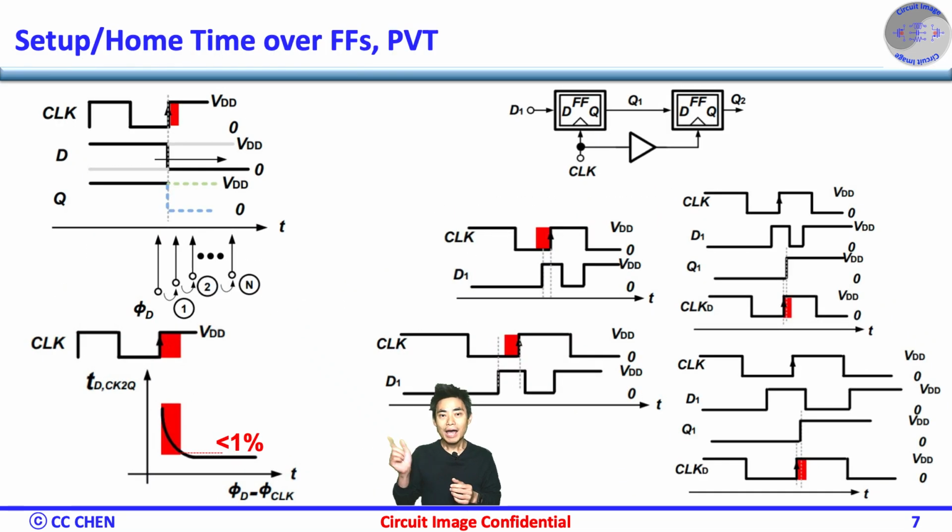Great. After the rising edge of the clock, you should move the data transition, high to low, low to high, on the same test bench. Then you should get the same behavior as the setup time. Clearly, you can define the hold time requirement at the corner of the flat region marked here. Usually, I prefer to make a strict constraint for the hold time, since any data rate will fail if there is a hold time variation.